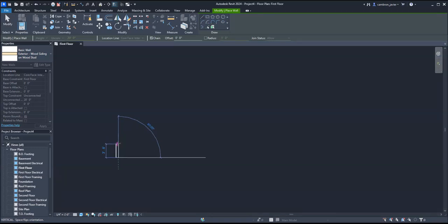So oftentimes people who are just starting off will go up and then move their hand to place the dimension or enter like a 6 feet 3. And when they do that, it'll angle off and people don't pay attention, and then they just enter dimension, and now you have a wall that is slightly angled, and you didn't notice it until it's too late and you're going to have to go back and delete it, right? So instead, what I want to do is go up, make sure the cursor's up, or the wall is up, and then I'm just going to type in, let's say 6'3".